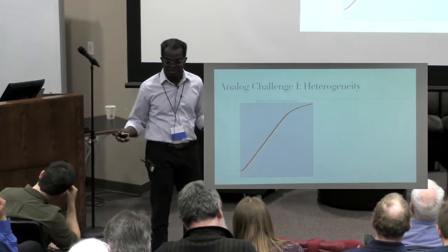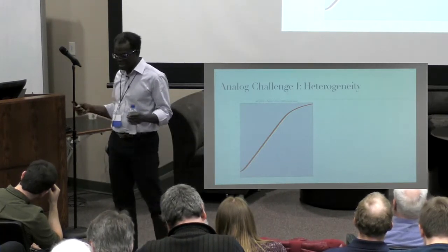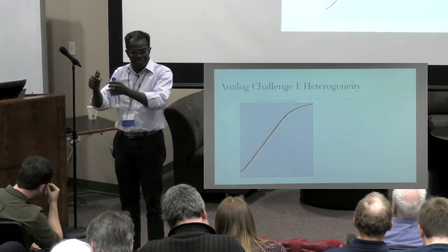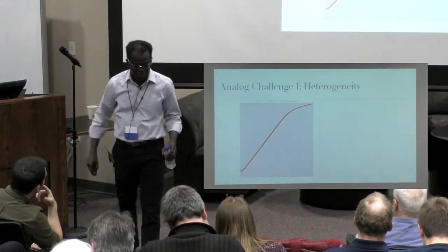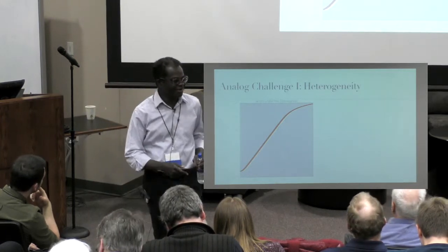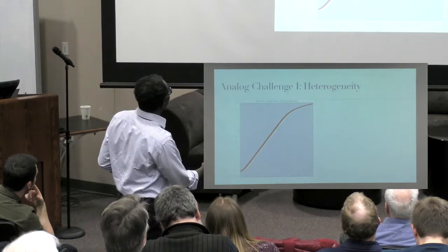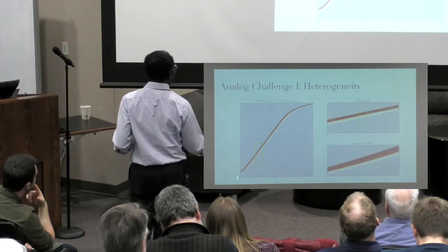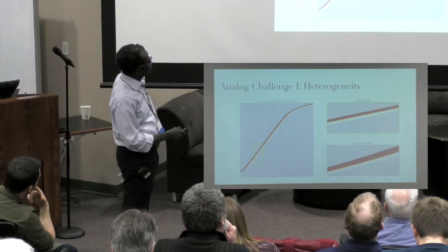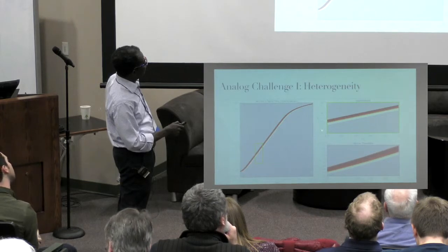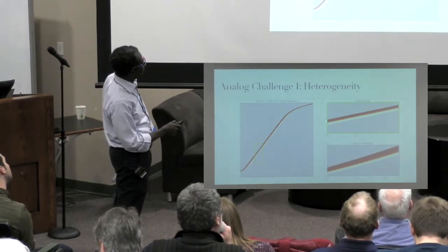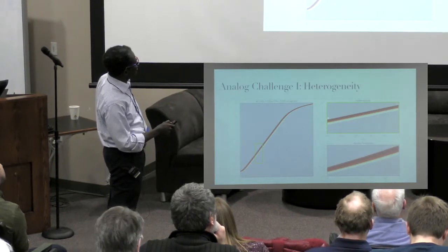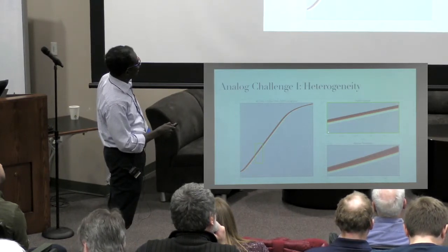So the guys at Albany do a heroic effort, but they can't place each atom one at a time. They'll never make any money, so they spray them on there. And that's what you get. So there's some tolerance. And so if you zoom in to this part in the subthreshold region, you'll find out that this fuzz, this is 2 decades from here to here. The amount of current that these 1,000 transistors are passing spans a decade, even though they're getting the same gate voltage.